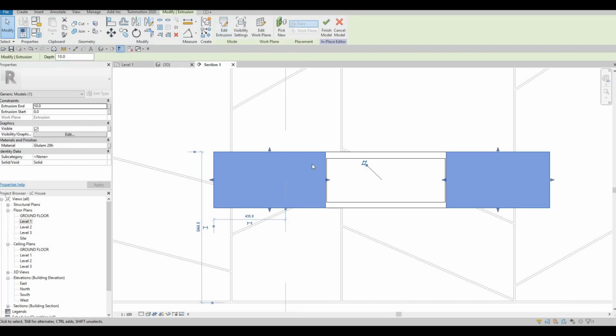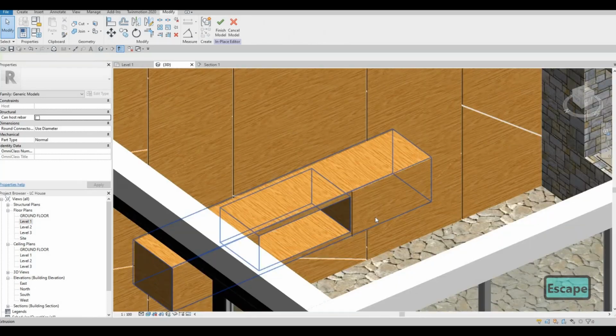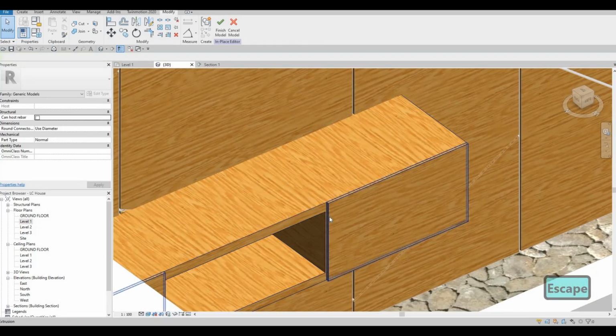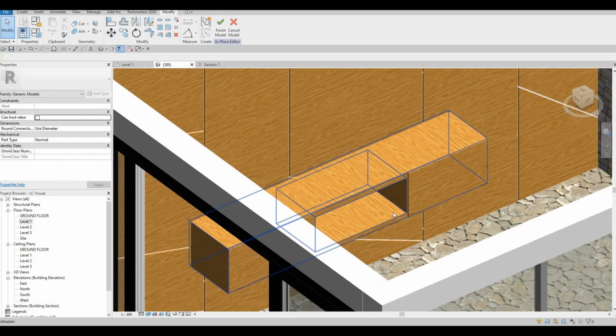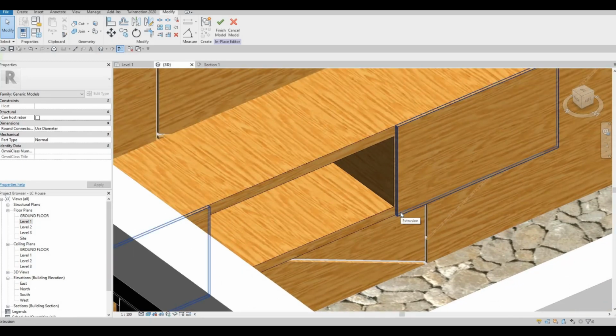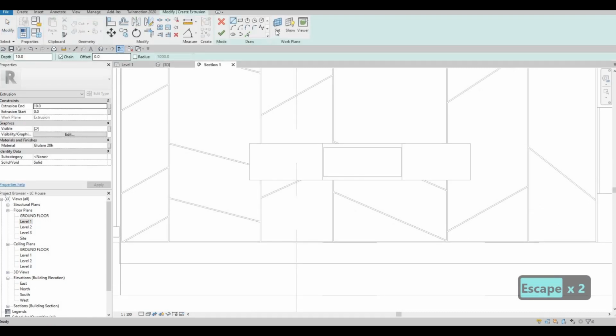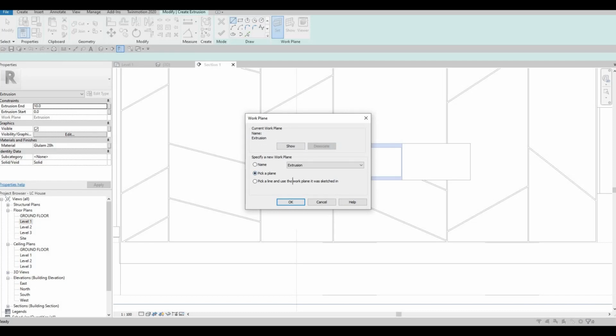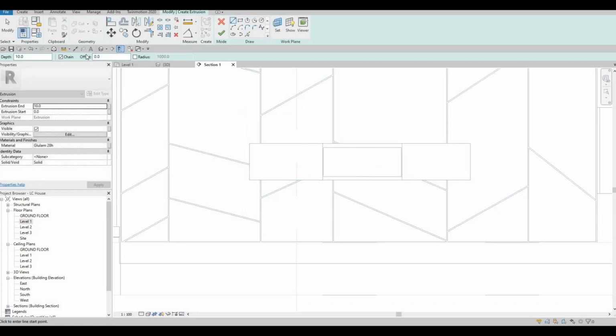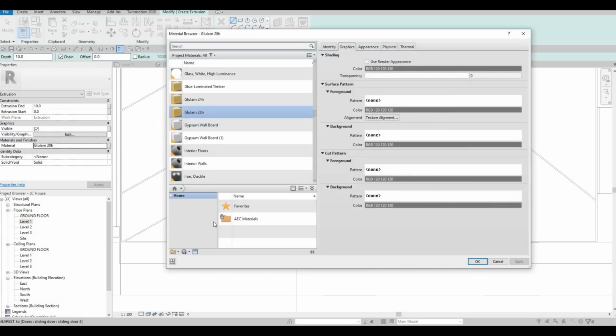And if we see it in 3D, it's just a basic front of that. And just a notch in there. And then what we could do is we could just add a metal piece so that it could open, flip. So we could just do that simply by going to section again, create an extrusion. You will need to set it again, pick a plane, and let's add it right here. But at the same time, it will be a metal finish.